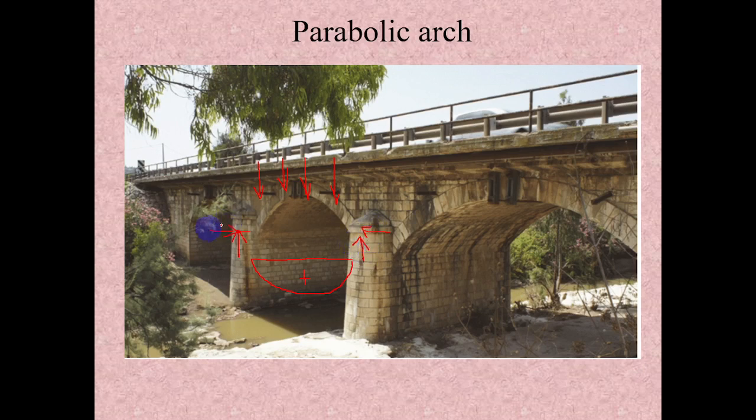So due to this horizontal reaction, it will create a counteracting bending moment diagram something like this. Let's say this is negative, not positive. This is the negative bending moment diagram. If you see both diagrams, more or less they will be equal. So if I superimpose this diagram, it will almost match with this, or maybe it will follow a path something like this.